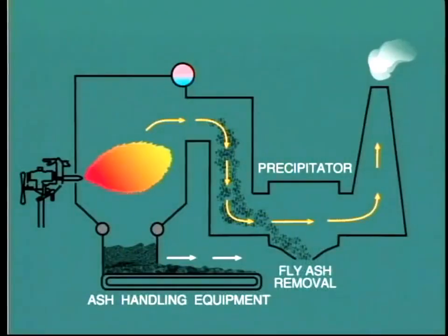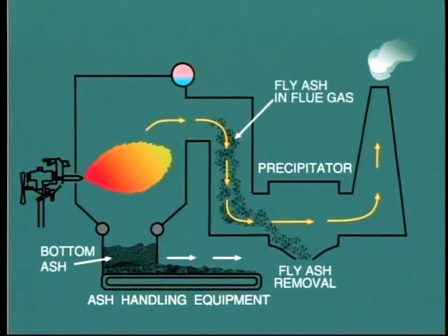We know that coal contains a considerable amount of ash. What happens to this during combustion? Well, the heavy particles fall to the bottom of the furnace where they are removed by the ash handling equipment. The lighter particles, known as fly ash, pass on through the boiler in the gas stream to be removed in the precipitator or other particulate removal equipment. We'll be looking more closely at this subject, particularly in regard to slagging problems, in the next module. Now remember, here we are only looking at the main features of combustion equipment and not the fine details. You'll need to thoroughly examine the schematics and equipment in your particular plant.